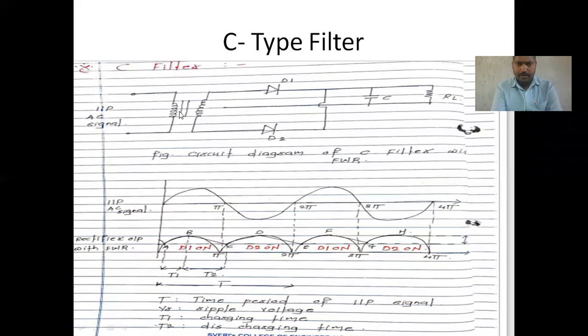So during the negative cycle, plus minus changes to minus plus, so that reverse voltage appears across your diode D1, and that's why it is not conducting now. Now see, minus plus.